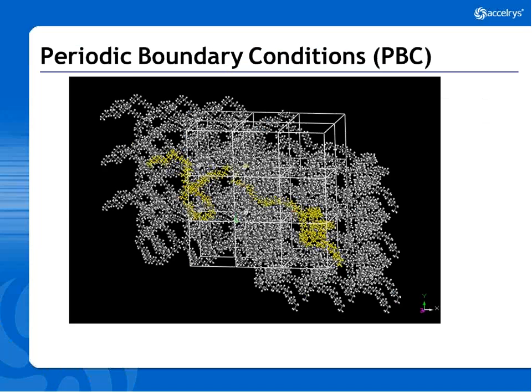So I can do minimization on a periodic structure or an amorphous cell structure of a polymer. It's considered the center of a 3x3x3, i.e. a 27-box grid, where polymer chains that extend through the boundary face become re-entered through the other face, where van der Waals interactions can be considered across the boundaries, where obviously you have to take care of charge representations within the system, so that allows me to do that, right?